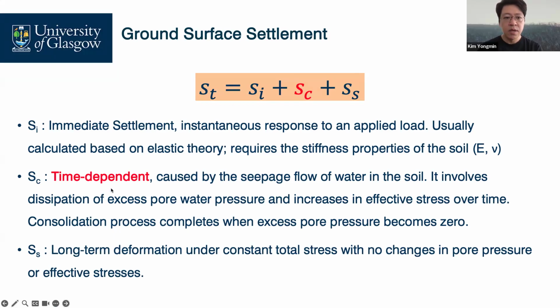Water drains out from our soil, and at the same time the soil is squeezed. The secondary settlement is a little bit longer-term deformation compared to our consolidation settlement. So we focus on consolidation settlement.